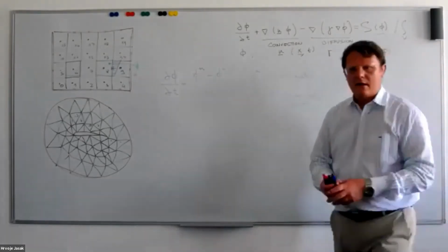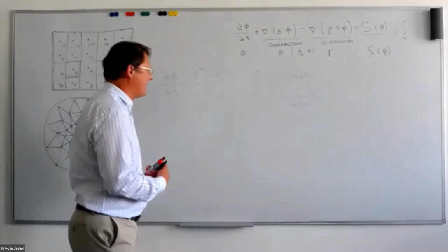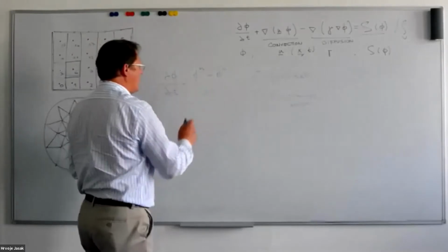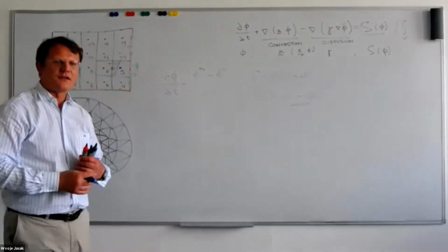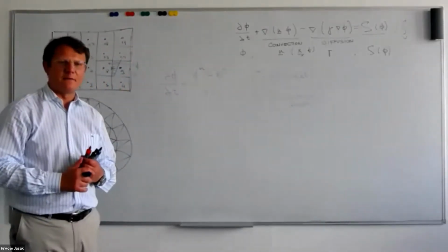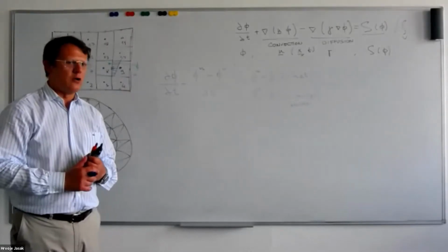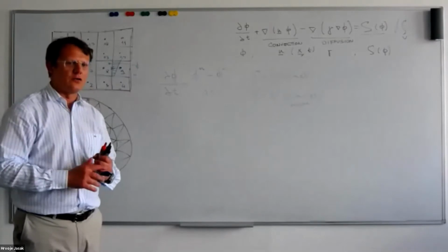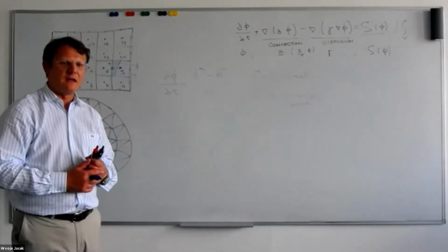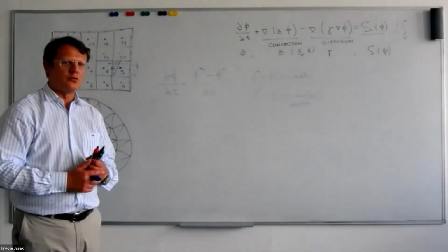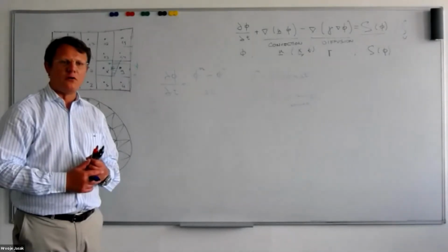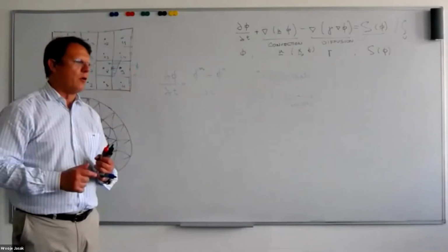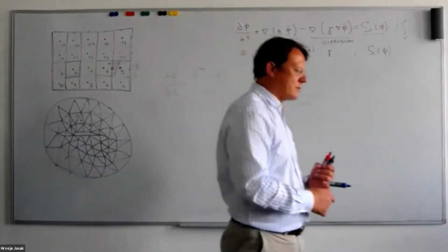So how can we evaluate the temporal derivative from these values? Phi new minus phi old over delta t is simply a finite difference evaluation. We also can introduce higher order interpolation, like the one on the slides, which reads d phi by dt is 3 over 2 phi new minus 2 phi old plus 1/2 phi old old, which is basically a parabolic fit through 3 values.